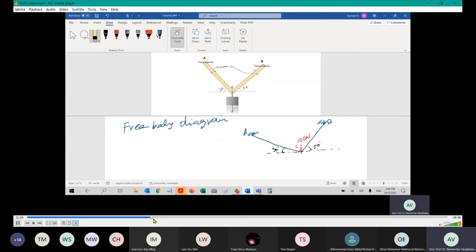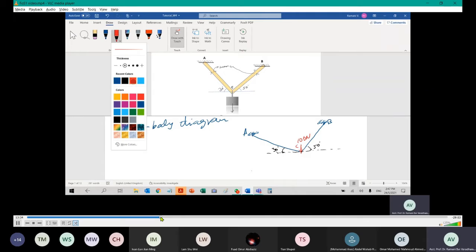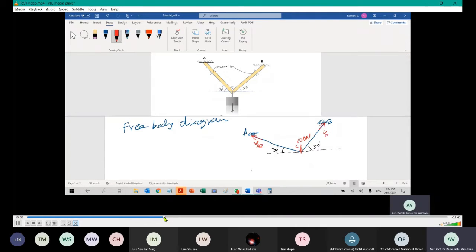because of the load acting at this point, you may have a reaction, a vertical one, right? It's vertically supported by this. Because of that load, there will be a reaction. I call this RA, or for convenient marking, I take the shear force as VAB, the member AB. And similar to this one, because it's downward, it may be upward like this, VBC, okay? At each point, we will see what they are one by one.